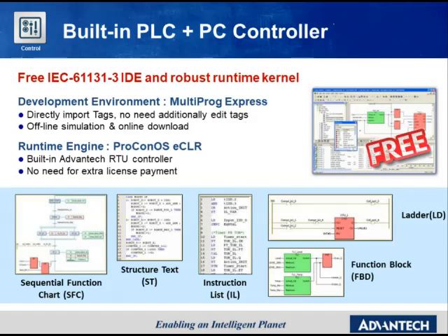With the help of Multiprog Express and PCLOS, ADAM3600 could support the IEC 61131-3 standard, and it supports 5 different PLC languages. For example, it supports sequential function chart, structured text, instruction list, ladder diagram, and function block diagram.